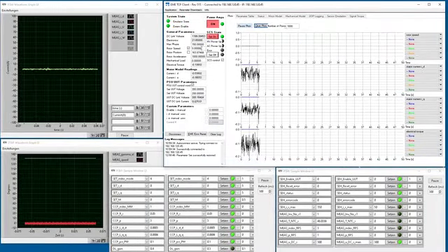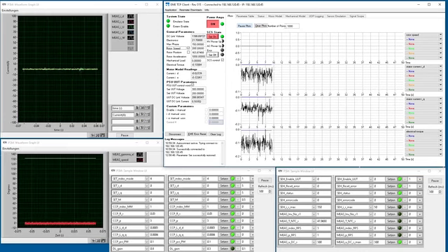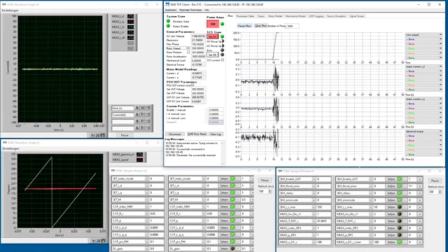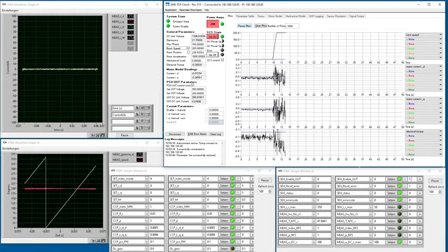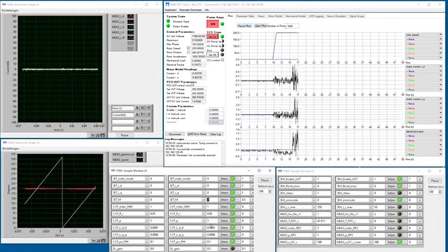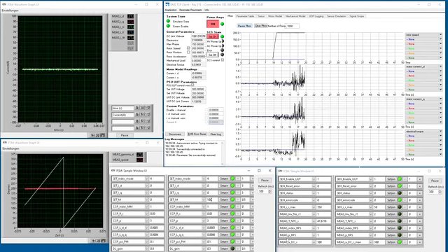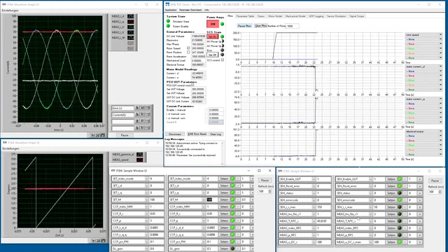Now we would like to perform the torque controller test with the power HIL system. The initial rotor speed is set to 200 rpm and the initial torque set point is 0. Then the inverter is enabled. The torque set point is set to 100 Newton meter. It can be seen in the plot that the actual torque follows the set point immediately.